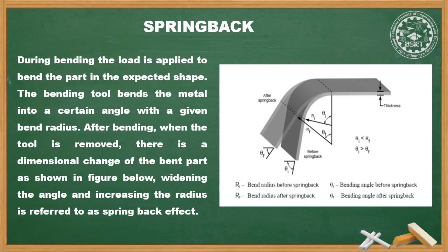The outer surface of the material is subjected to tensile stress which propagates inward towards the neutral plane. The inner surface of the material is subjected to compressive stress and it propagates inward towards the neutral plane. This means that the metal near the neutral axis has been stressed to values below the elastic limit. This creates a narrow elastic band on both sides of the neutral axis. The metal far away from the neutral axis may be stressed beyond the yield stress and has been plastically or permanently